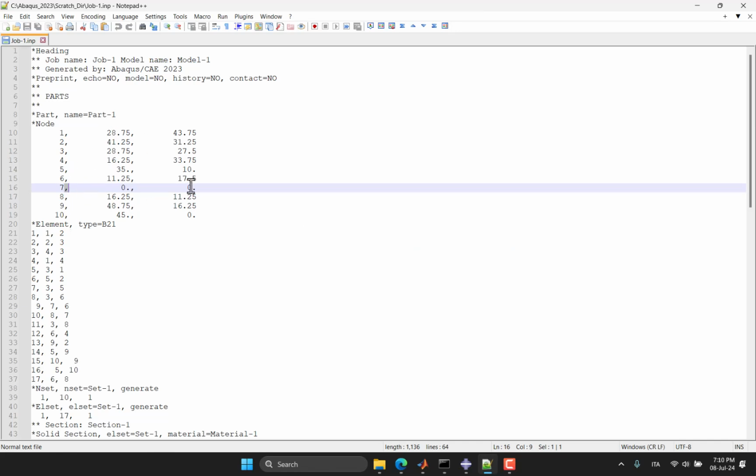But of course, you can modify them, you can write your own matrices. Now I'm telling you what those matrices are. In the first column you have the number of the node. So for example, this row is defining node number 4. In the last two columns you have the x and y coordinates of the node.